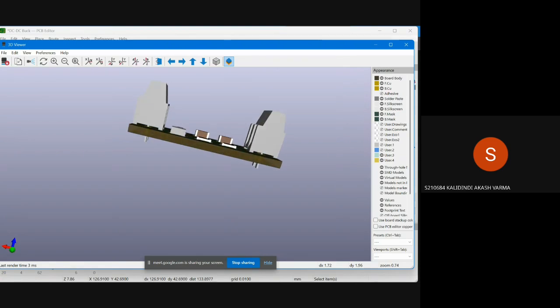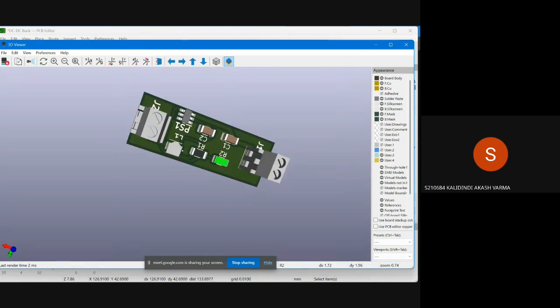On the top layer, there are very few components. No track can be overlapped with any other track, otherwise crosstalk and short circuit will take place. The components are also lower in count. This is the power track, which has a higher width, and these are the signal related components. That is about single layer PCB.